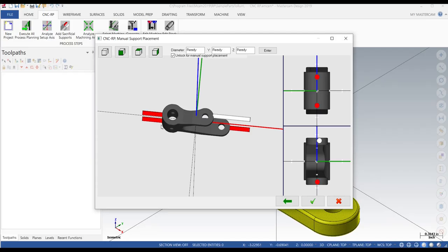You will also have to remove the supports after machining, and this could, depending on your method, result in a lot higher tolerance error level and affect the feature of your part. For that reason, I always choose the least important features to attach my supports to. That way, even if I slightly mess up taking them off, the part's still pretty good.